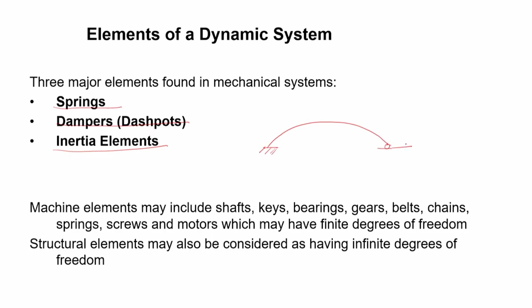Then if I have to design it in terms of spring, dampers, and inertia elements, we can consider that it is going to have not just 1 or 2 degrees of freedom, but a countably infinite number of degrees of freedom in this system, where each element is joined with the other element, and in their intersections we have the degrees of freedom present, and these degrees of freedom are constrained by either some springs or dampers or some inertia elements.